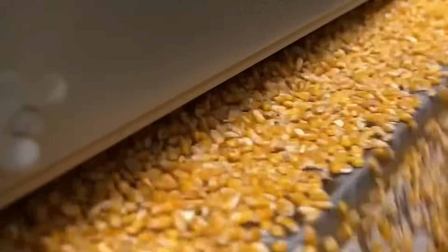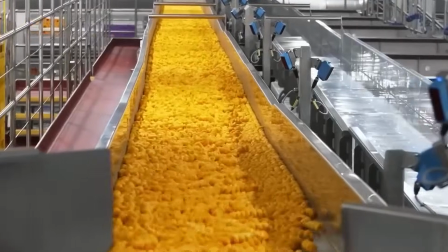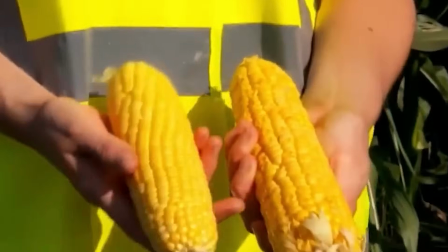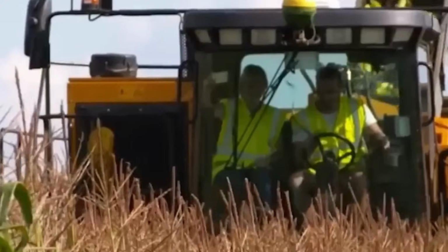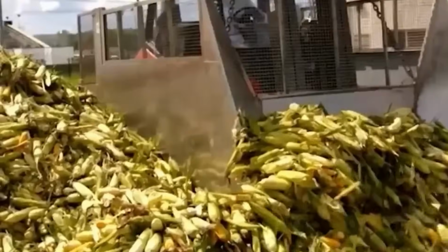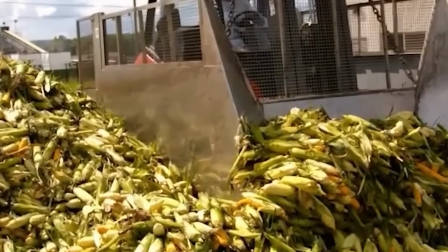The vertical form-fill seal system uses film rolls printed with product branding. The film is fed through a forming collar, sealed longitudinally, and then sealed at the top and bottom to create a pillow pouch. The filled bags pass through a check weigher and metal detector. Packages outside the weight tolerance or those triggering metal detection are automatically ejected via pneumatic arms. Conforming bags are grouped and conveyed to case packing robots.